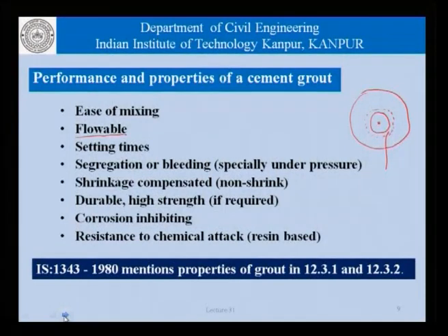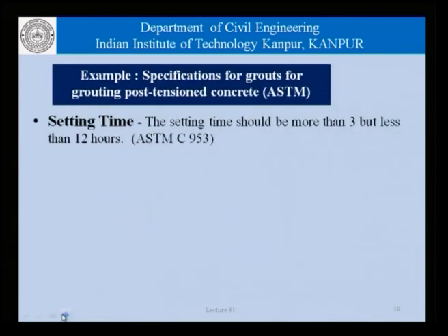As far as specifications are concerned, for example, in India, IS 1343 mentions some of the properties that are required as far as grouting in pre-stressed concrete construction is concerned, in sections 12.3.1 and 12.3.2. As far as ASTM standards are concerned, some performance parameters are that the setting time should be more than 3 hours, but less than 12 hours.